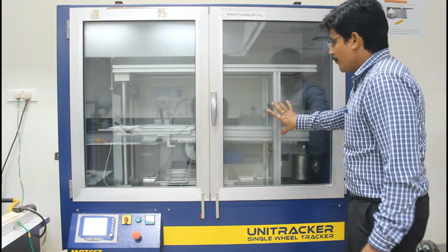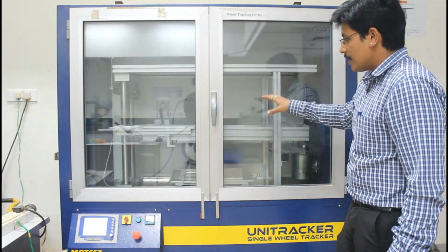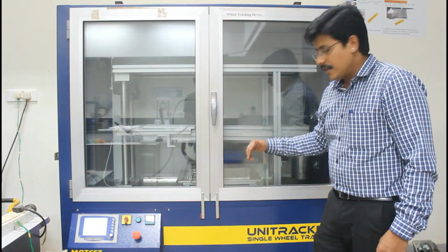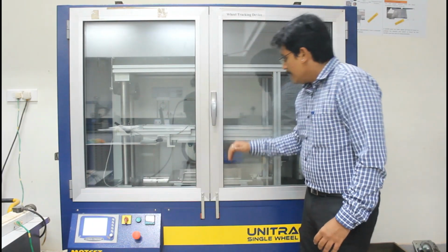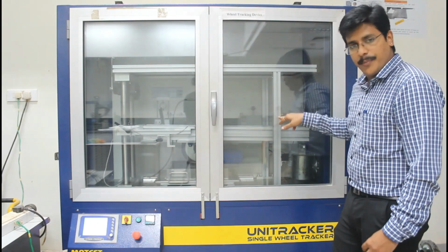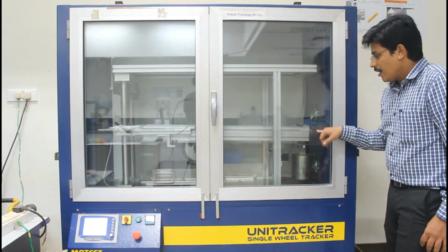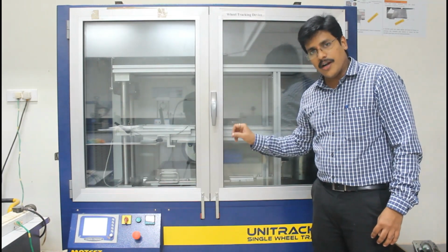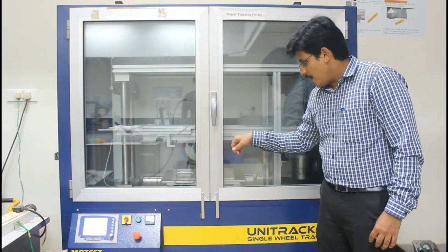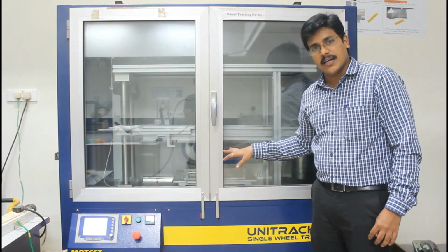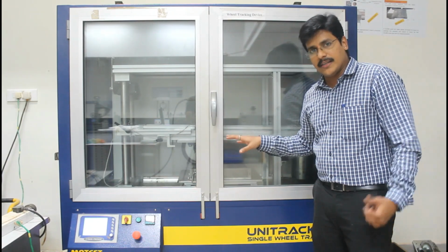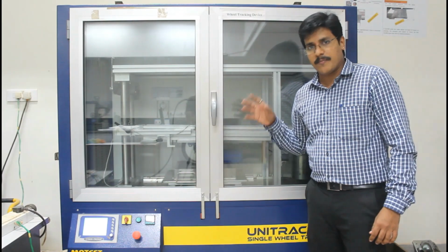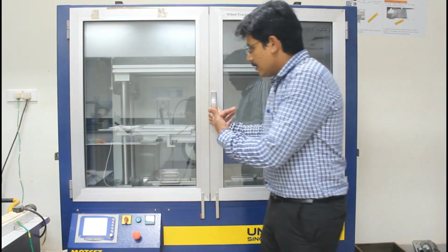So now if you see here, actually if you open that door, it will stop. You can see here how the table is moving to and fro, right? The table moves to and fro, right? This particular cantilever beam has a load here, right? Now the load on the sample is around 70 kg or 700 Newton, right? So that load is applied on the particular bituminous mix. Now this bituminous mix can be compacted in the roller compactor, which we will show, to required density and required air voids. So if you open the door, the test will stop, right?